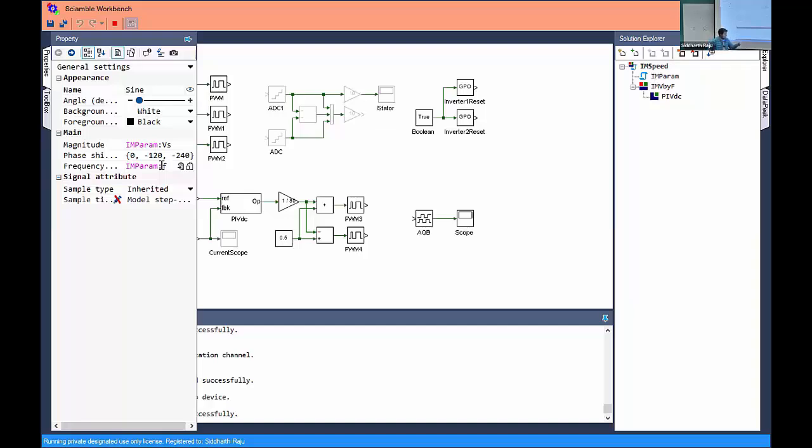You can directly take an induction motor and connect it to the wall outlet, a three-phase wall outlet, and the motor will start rotating. All right, and it'll go to the speed that it has to go to for the particular frequency. And then in the industry, if you start applying more and more load torque, and the motor comes to a full stop, it's not going to damage the motor. You reduce the torque again, and the motor will start back up again as if nothing had happened.